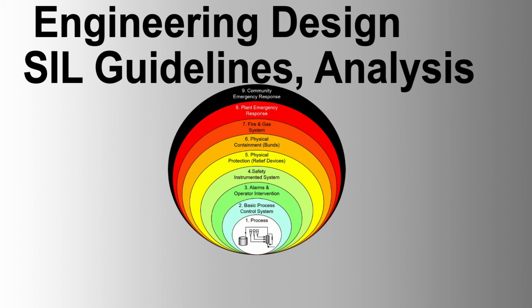Redundancy and voting configurations. Redundancy: using multiple components to perform the same function to improve reliability. Voting configurations. Systems can be configured in various voting logics, like 1oo1, 1oo2, 2oo2, 2oo3, etc., to enhance fault tolerance.